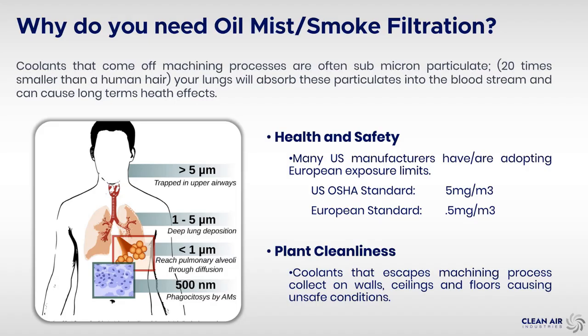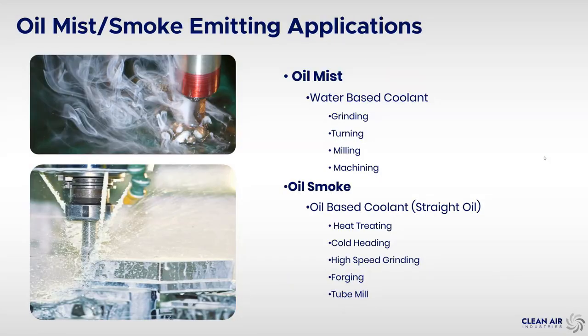But what happens is the coolants and the mist will escape the machining processes, and it just gets all over the floors, all over the ceilings. And besides the health hazards it causes, it can cause unsafe conditions in the plant as well. So oil mist actually comes from water-based coolants, and your oil smoke comes from straight cutting oil.